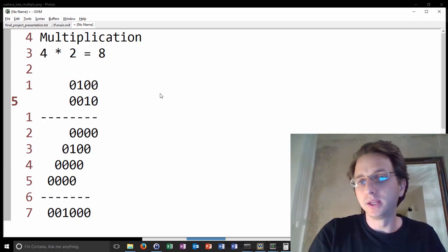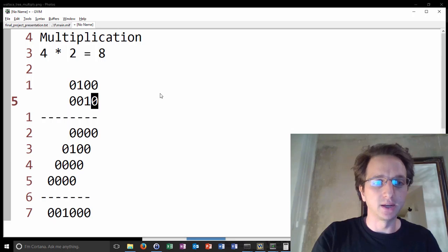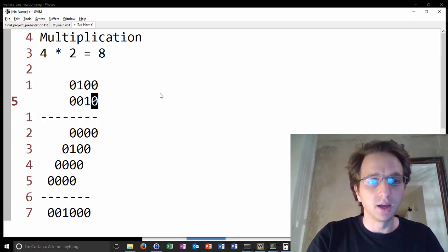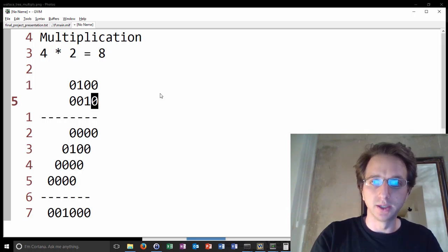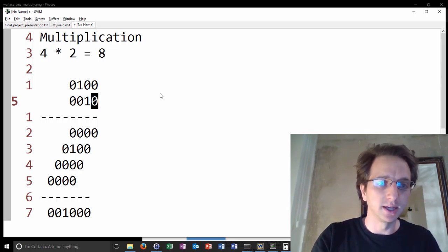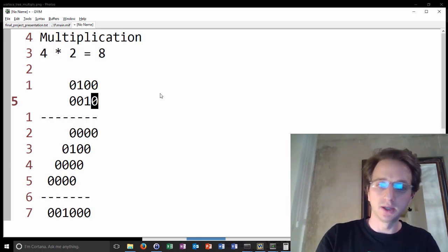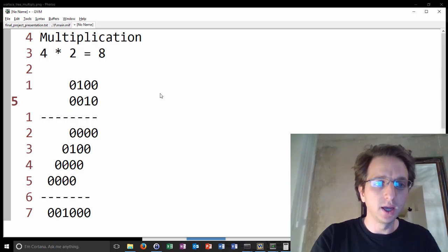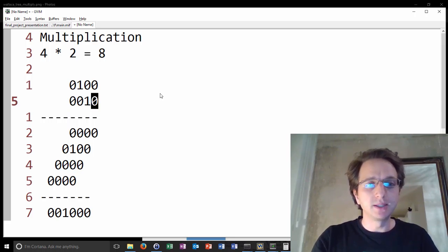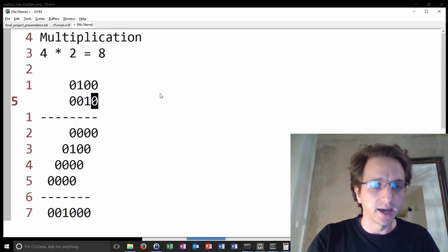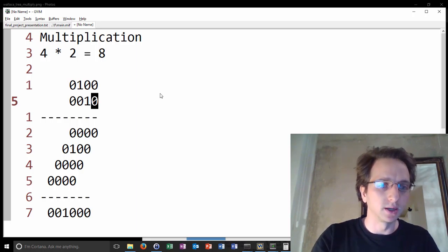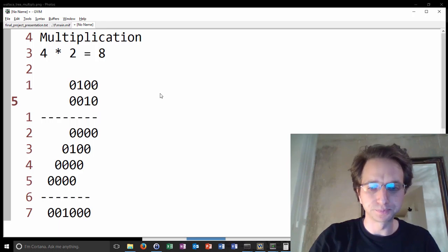The way that we did it in class is that we would take each bit in the multiplier, and if it was a 0, we'd basically carry down the multiplicand, and then for each bit of the multiplier, shift the multiplicand 1 bit to the left, and if it's a 1, propagate it down. That means that in this 4-bit multiplier, I have 4 partial product sums before I'm able to get my answer.